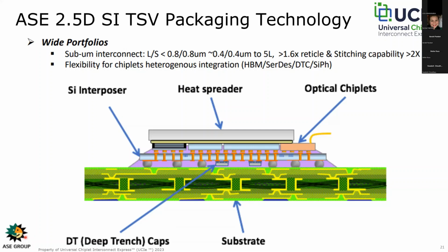This slide here shows a cross-section of the ASE 2.5D technology with the TSVs. So you can see the substrate, silicon interposer with integrated deep trench capacitors for decoupling.